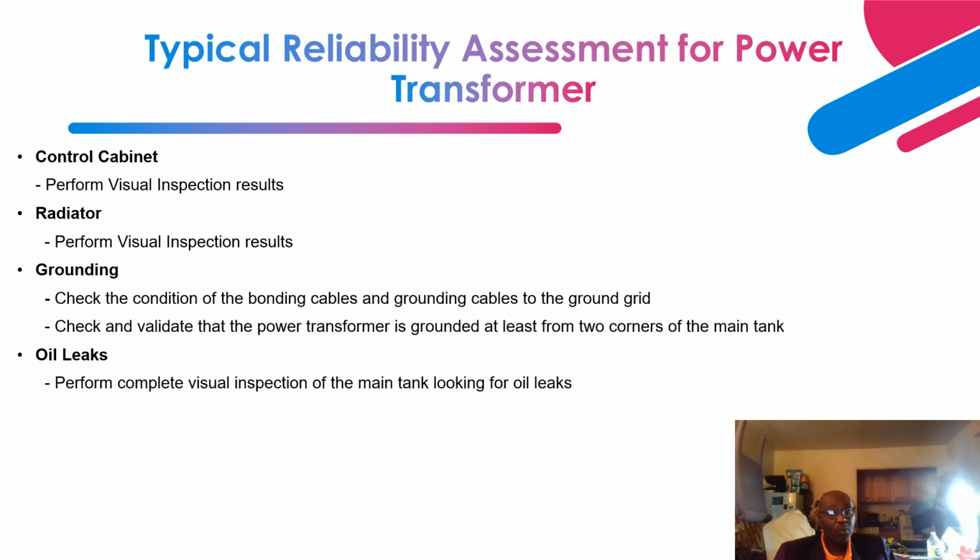Because what is the reason why I'm saying that? If the leak has to be further fixed by maintenance and operations, it helps them to locate it quickly, and it will also help them know what you're talking about. And a lot of the leaks with radiators are around where the butterfly valves are.